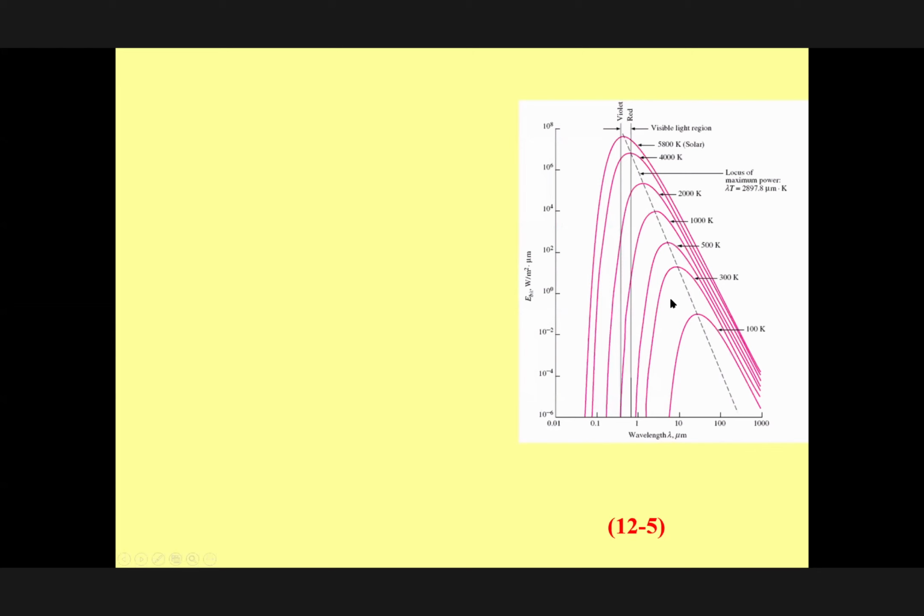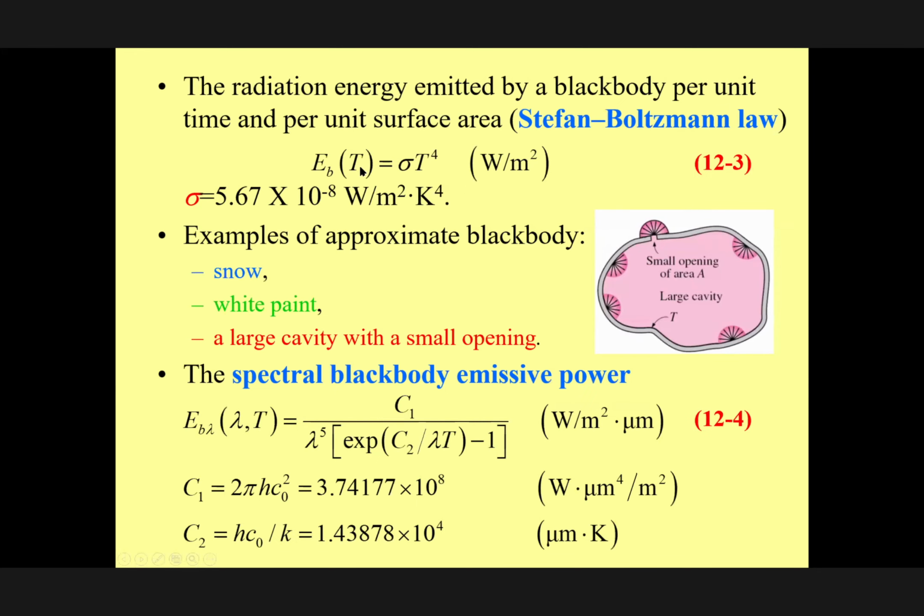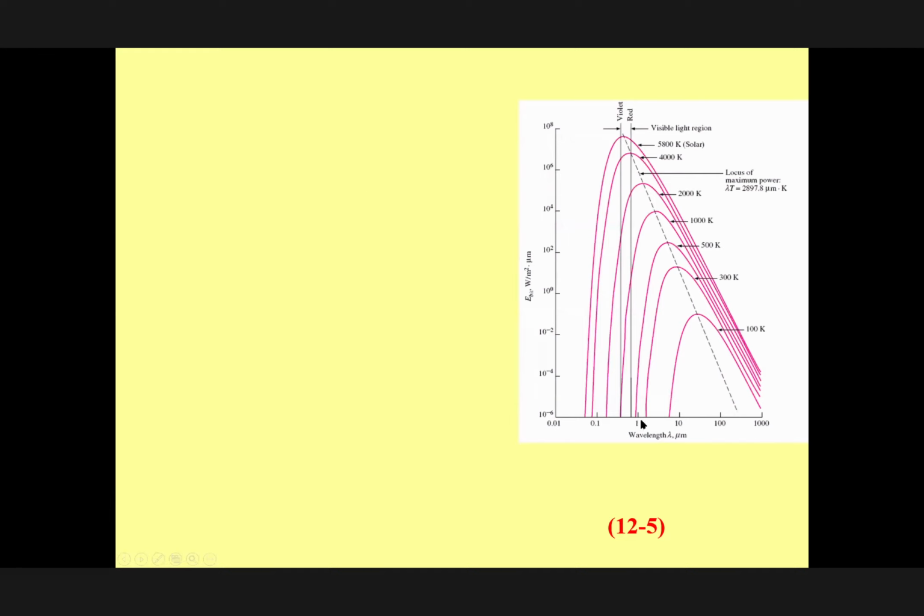The total area gave me this amount here. Okay, this is the total area, the emissive power from 0 to infinity. Here it is given as a function of wavelength, but if you calculate the total area, it gives you the total. And when we talk about the energy coming from the sun, that last curve represents it. We can assume the sun is a black body at a temperature of 5,800 Kelvin.